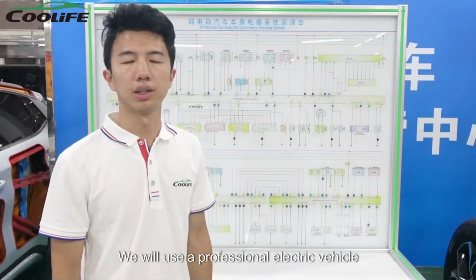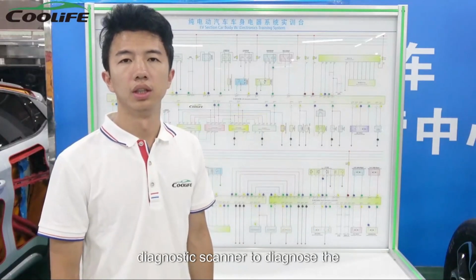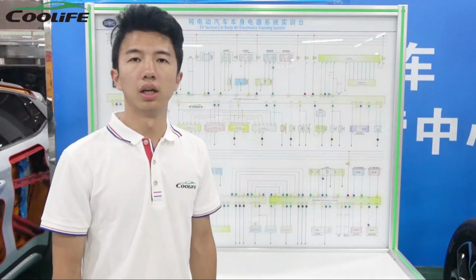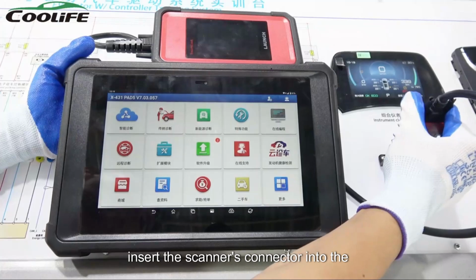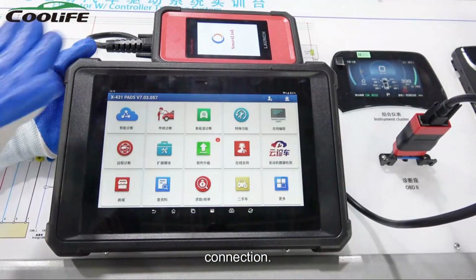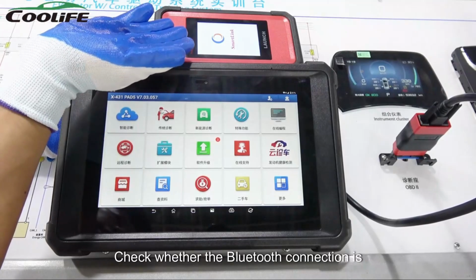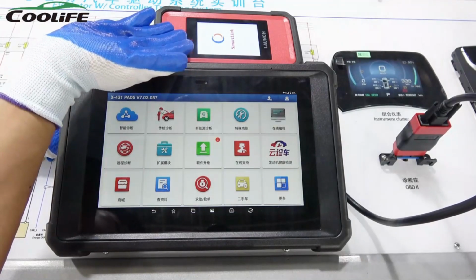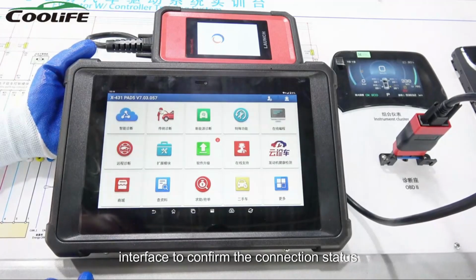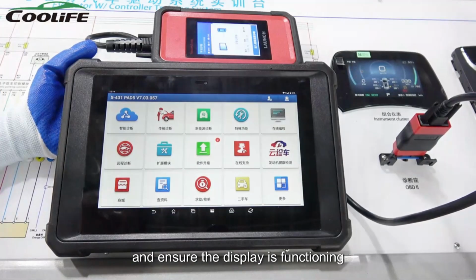We will use a professional electric vehicle diagnostic scanner to diagnose the equipment. The specific steps are as follows. First, insert the scanner's connector into the equipment's OBD port and ensure a secure connection. Then, check whether the Bluetooth connection is successful. Finally, observe the scanner's display interface to confirm the connection status and ensure the display is functioning correctly.